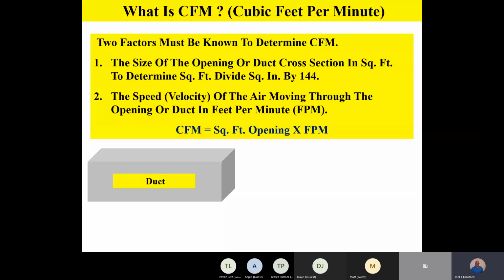So this 22-inch round duct, let's say it was the main trunk on a 5-ton unit, would be sufficient for a 5-ton unit based on 400 CFM per ton cooling and a design velocity of 760 in our example. If that's an acceptable velocity on a main trunk, which it is, and we'll look at those tables a little bit later on, that would be sufficient for a 5-ton unit. A 22-inch round metal pipe, insulated on the outside, would be a good duct size for a 5-ton unit.